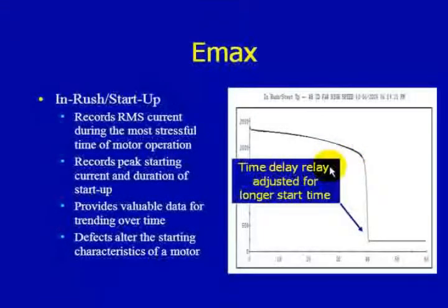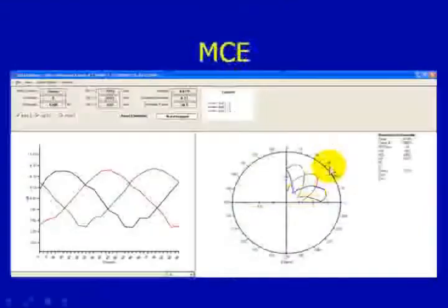So if you have a process that you want to look at for 60 seconds, essentially we're just taking a current sample, and you can monitor that process over that 60 seconds, maybe a motor operated valve or something of that, making sure that the events when they're designed to happen actually do happen based on the current that it's drawing. And you can look at if a motor takes maybe a little bit longer or shorter to start up, that could be also attributed to rotor bar anomalies or load changes.